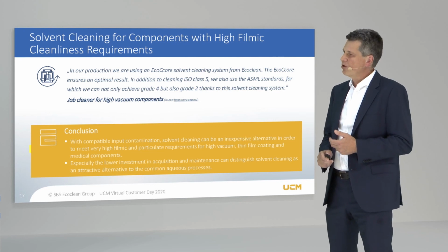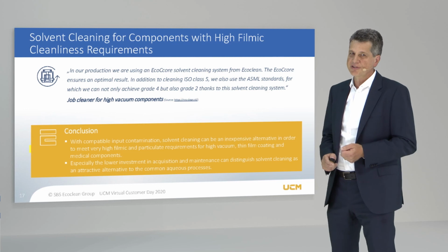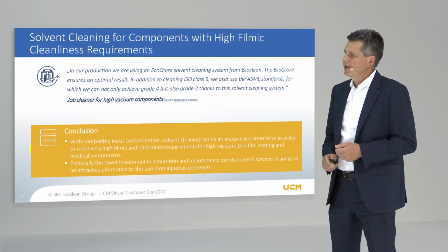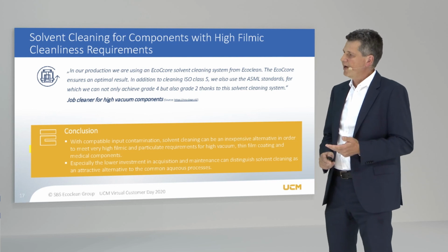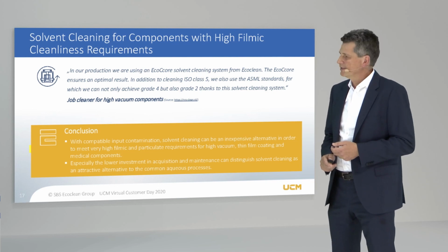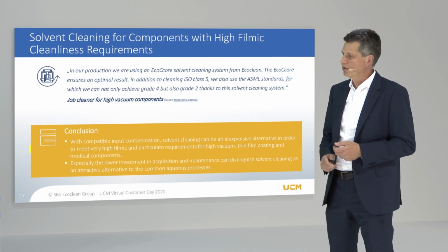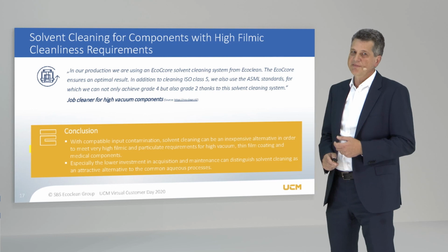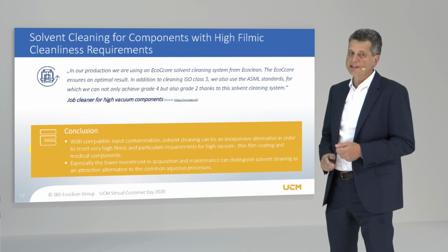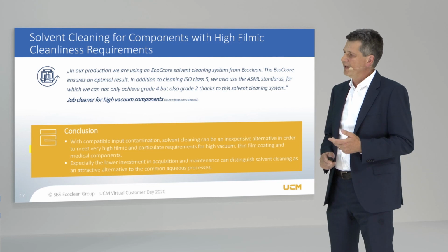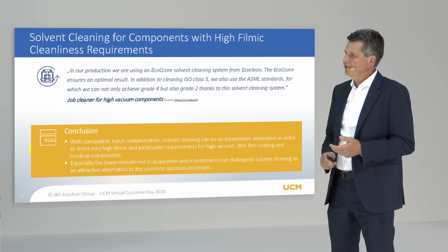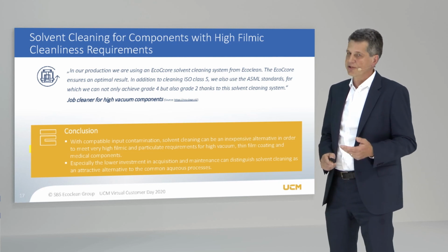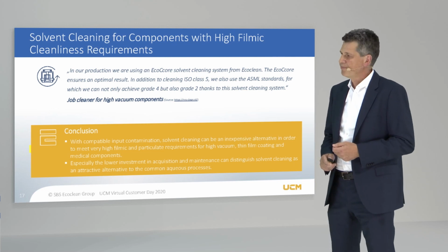The conclusion is, with a compatible intake of contamination, solvent machines can definitely be a solution to clean very high filmic particle requirements from the vacuum technology, thin film coating, and the medical components. Especially the lower investment costs and the lower running costs are a very appealing factor that makes the solvent cleaning systems definitely very attractive as an option or alternative to aqueous systems.